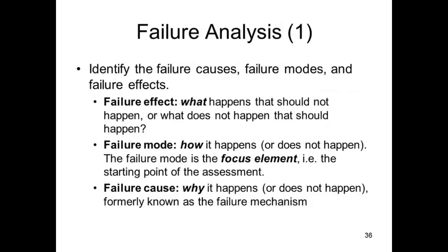The next step is failure analysis. We've seen where the failure causes might come from. Now we have to identify the failure causes, failure modes, and failure effects. The failure effect is what happens that shouldn't happen or doesn't happen that should. The failure mode is the focus element. That is, the focus element means simply the starting point of the assessment.